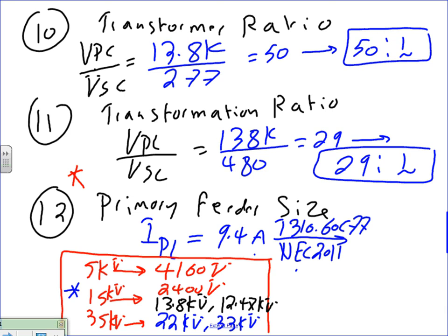You're going to find the size that you're going to use is 3 conductors. Why 3 conductors, by the way? 3 phase. The minimum size that you can use at this voltage is number 6. And the insulation is called medium voltage dash 90. This MV-90 is equivalent to your THHN or THHW.